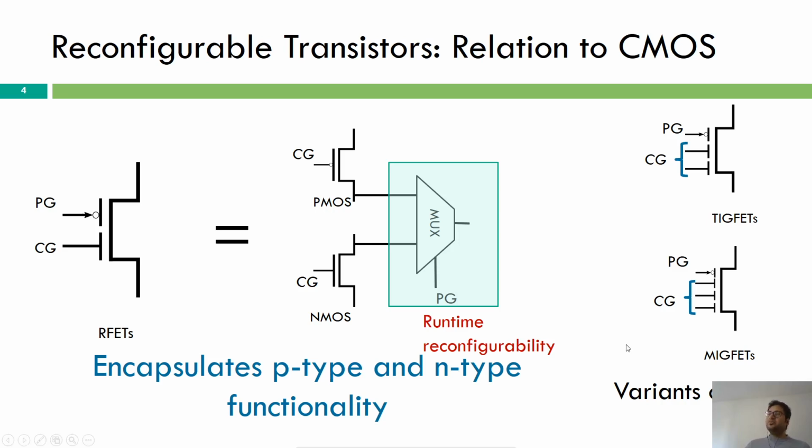But unlike CMOS, which has gate-to-drain and gate-to-source resistances and capacitances, these devices do not have those, and this allows us to make larger logic gates, which is not so easy or not so cheap in the traditional CMOS technology. So hence our paradigm changes now. We can't work with our traditional CMOS-based logic gates.